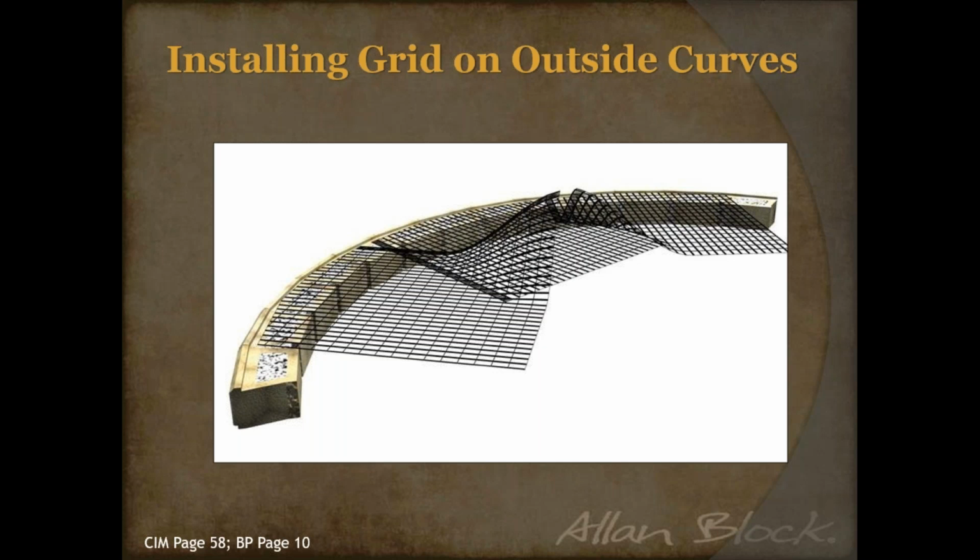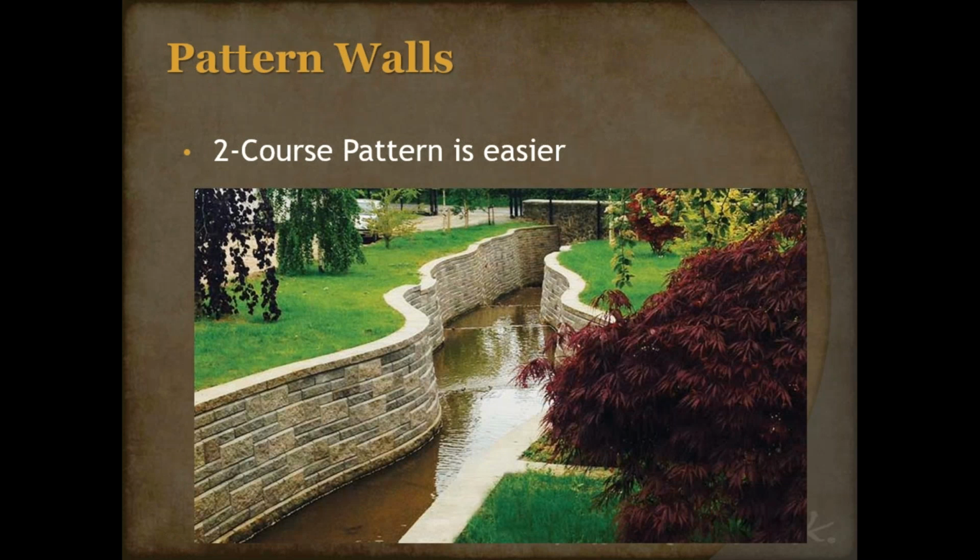We're in good shape. The last thing I want to talk about curves before I move on is when you do have the option to do a pattern wall, and I do recommend giving it a shot. It's one of the easiest ways to distinguish yourselves from competition and kind of take your projects to the next level. Here's a beautiful ashlar pattern wall in a stream area, but with patterns, you've got blocks that fit together, and we've got different preset patterns, whether it's 2 courses, 3 courses, or even a 4-course pattern. When you're doing curves, you want to use a 2-course pattern.